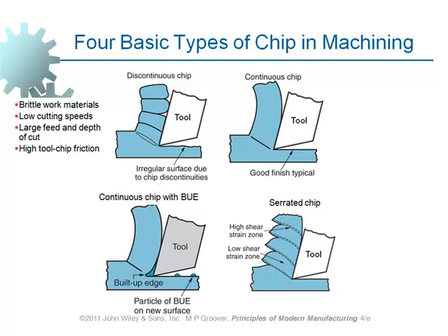Compare this one with the one on the right. Here, as you can see, we have produced a rough surface finish. But here, the surface finish is smooth compared to that one. And the type of chip which is being produced is continuous. So, what type of material gives us this type of chip? Brittle or soft?